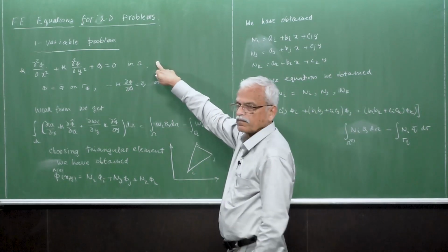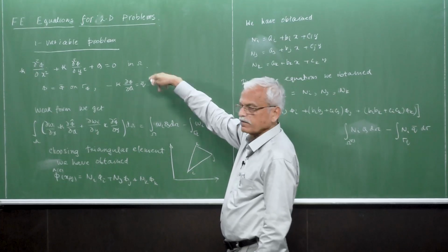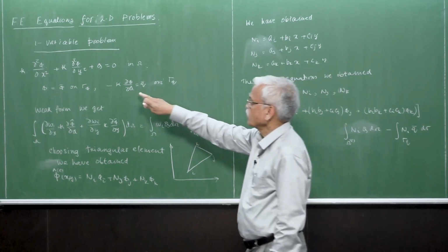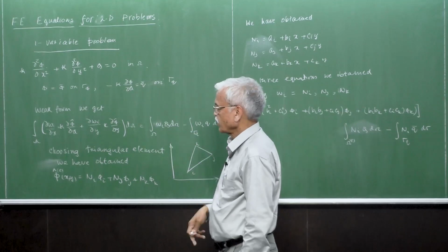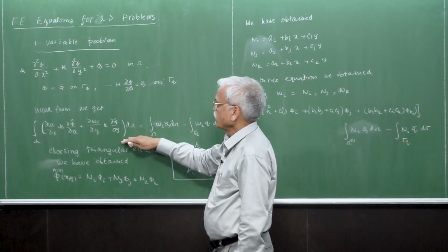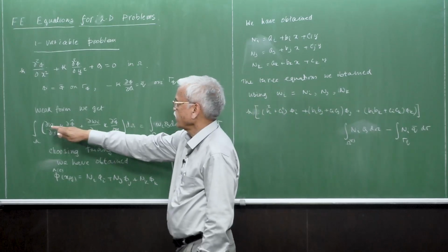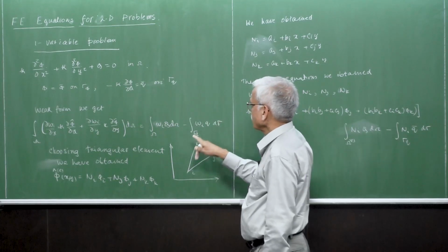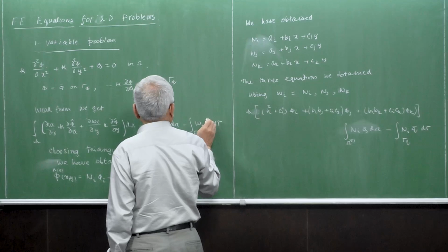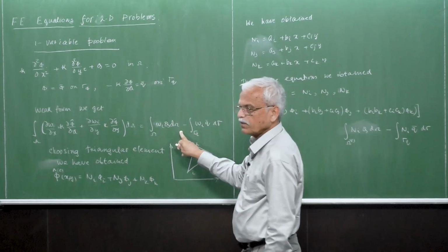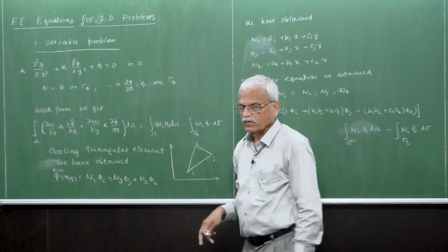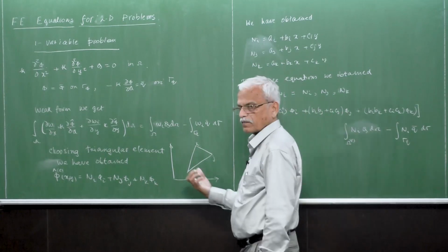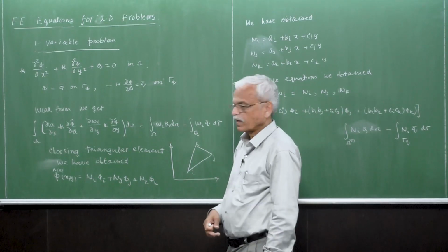If this is the basic governing equation, it is in relation to the heat conduction problem, because here we have the temperature, and we have the flux boundary condition. So this is a weak form. We have the weighting function W, and then we integrate it. A part of that has been cancelled with this one, leaving only this. And then we also have W Q d omega, where Q is the heat source within the body, something like electrical conductors.